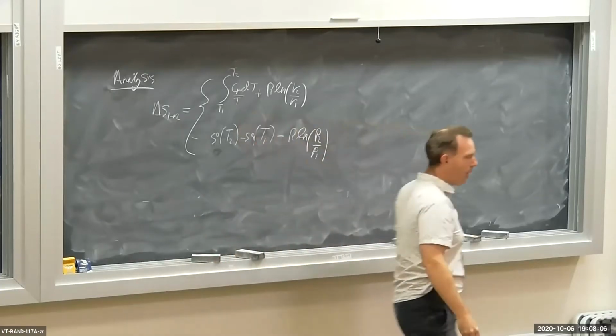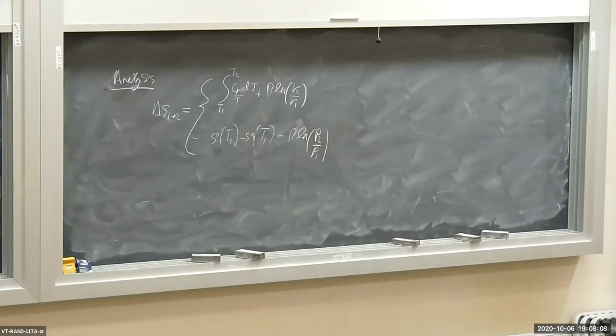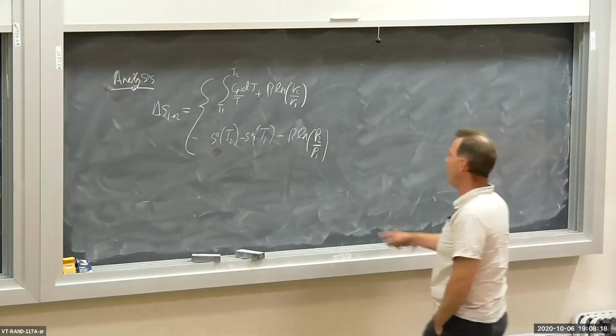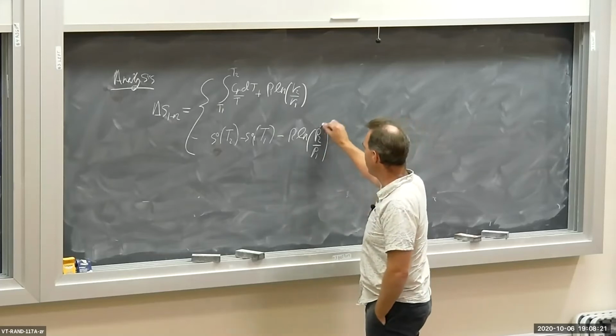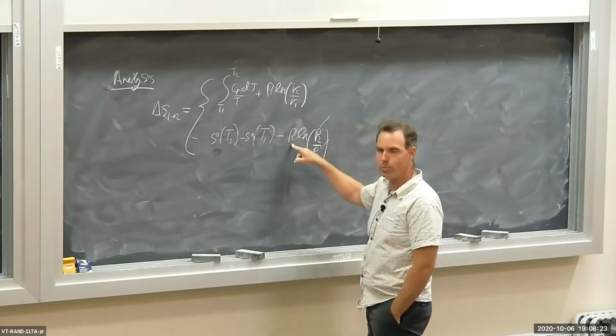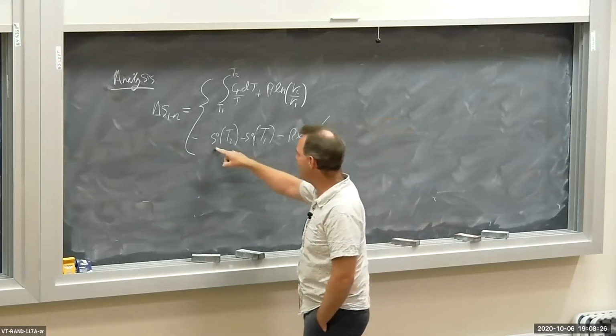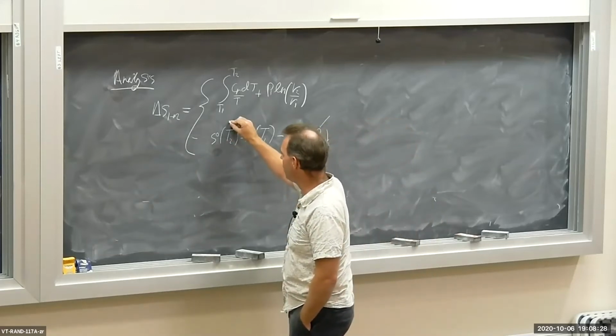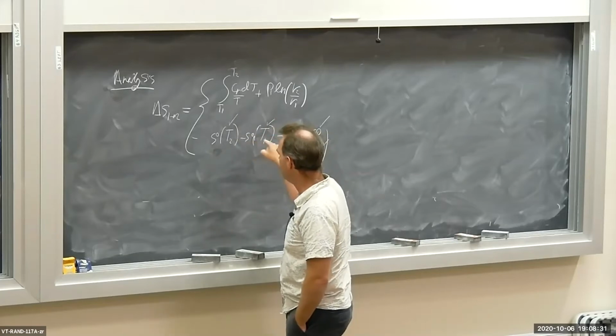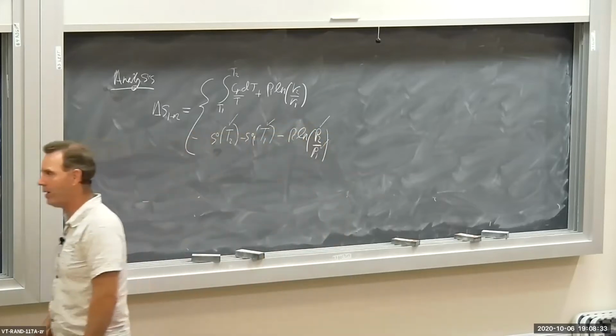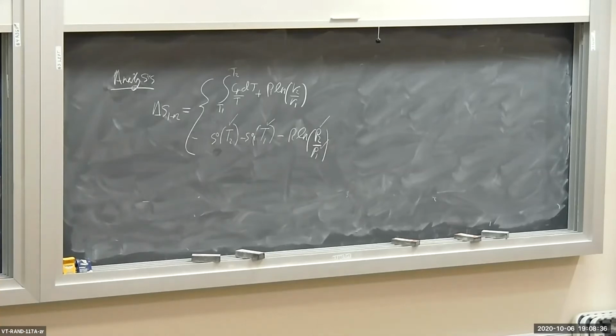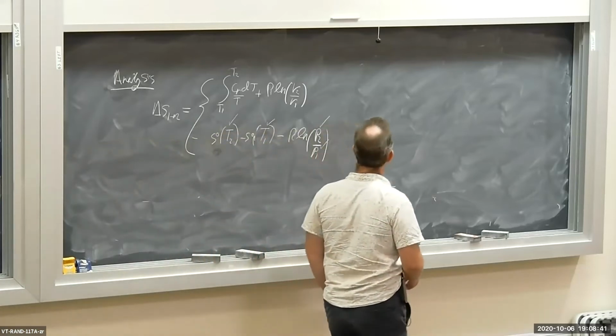So I have these two equations here. I can use either one. Clearly, the second one is most useful. The S naughts are in tables, IGB tables, and I'm given the initial and the final pressure. So I know the pressures. The gas constant is pretty easy to get. I can get that for air. And these S naughts, well, I can look them up on the table, but I also know T1 and T2. So I can look up these S naughts evaluated at temperature T1 and T2. So calculating delta S from the inlet to the outlet is quite easy if I use the second version.